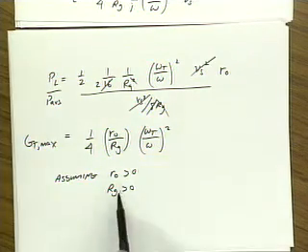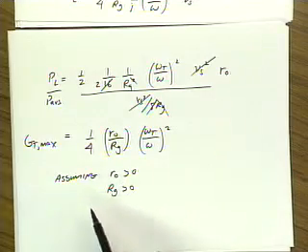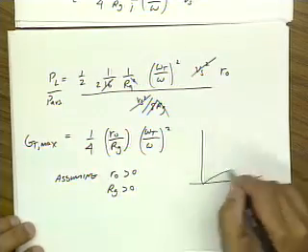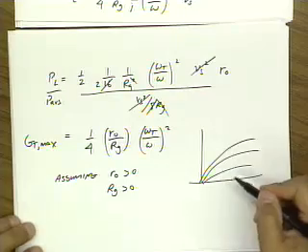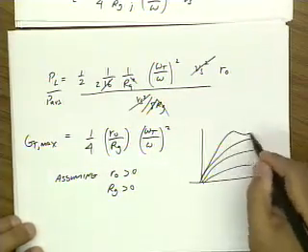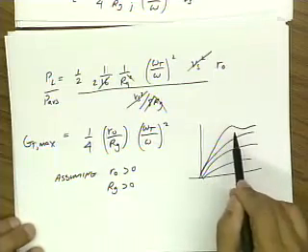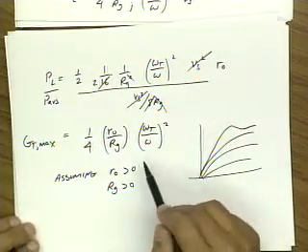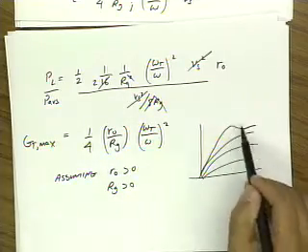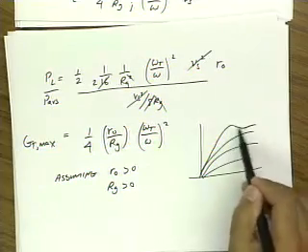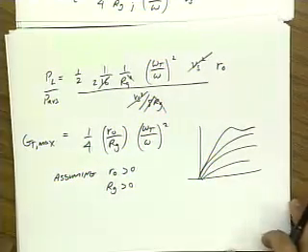That's actually interesting. Remember, Ro is not a physical resistance. Ro is the output impedance of our device. So for instance, if we look at our curves, if this slope is positive, that means that Ro is positive. But what if you had a weird kink in your curve, right? At this point, Ro goes negative, and that means that actually GT max, as we've defined it, doesn't exist. Because the device, under certain conditions, you can make the device oscillate in this region. Okay? We'll have a lot more to say about that later on.